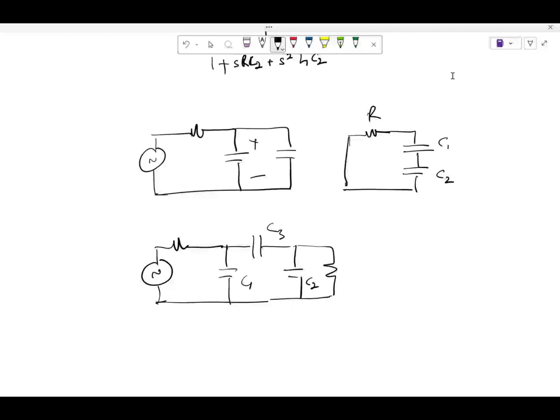What is the order of the system? Yeah, you have done this before. So why second order, or why not third order? Come again? No, without transformation. Let's say I do not do that. Initial conditions on two capacitors automatically. Exactly, right? So if I set the initial condition on this capacitor, the initial condition across C3 gets set. That's not an independent initial condition. So hence its order is 2. Okay, fine. So the order is 2.